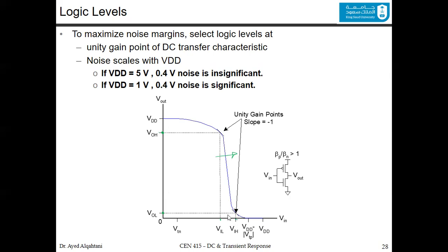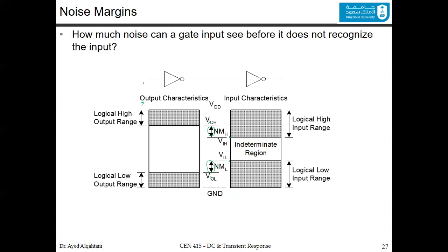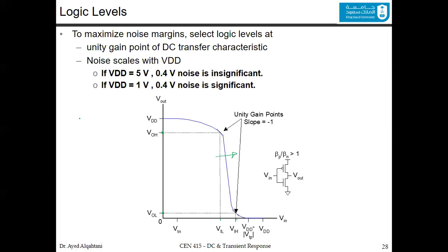Indicated, but what we discussed before is the VOH minus VIH. So VOH minus VIH. And you can see that the value of the VOH is quite large here. If you take this and you subtract the VIH from this part, you will end up with a kind of small value. And that is the noise margin at the high.